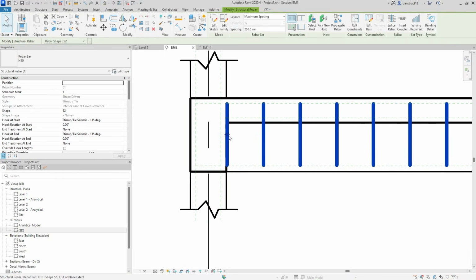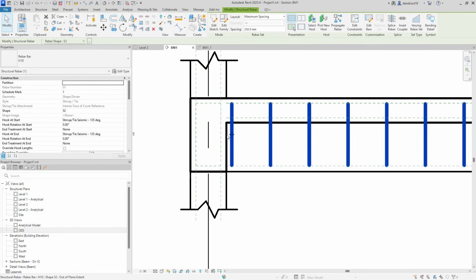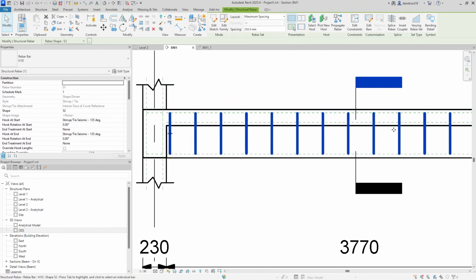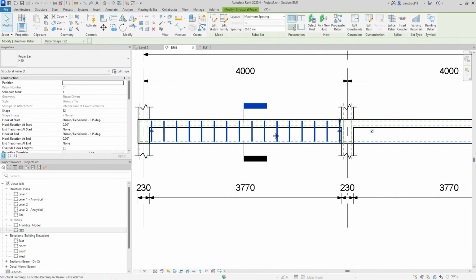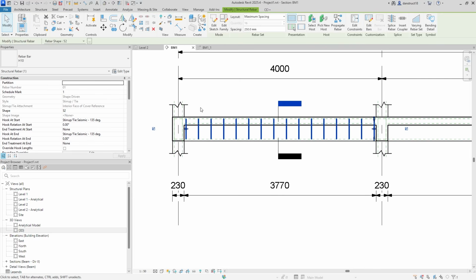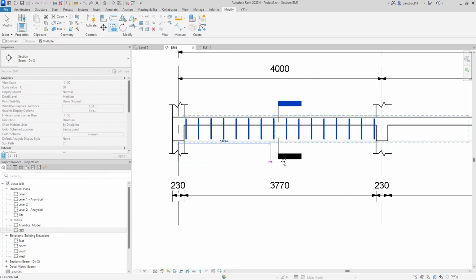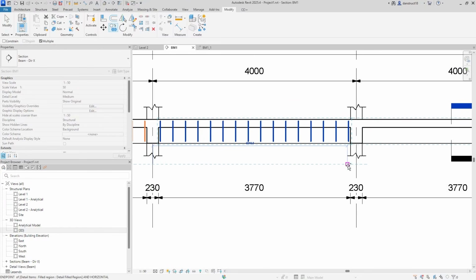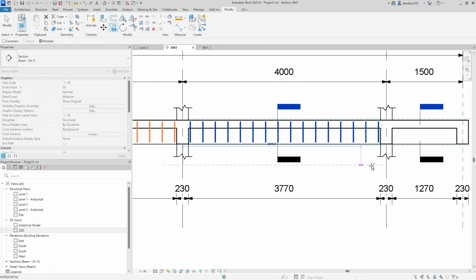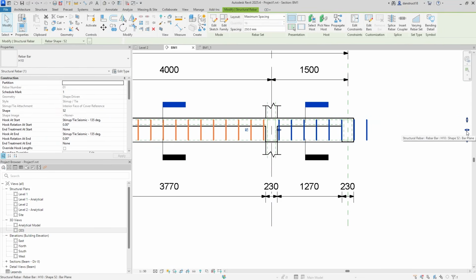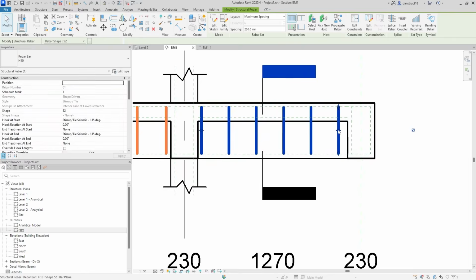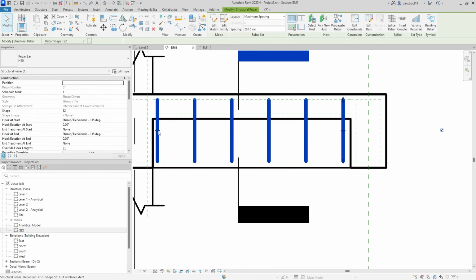Now I'm just going to go over here and adjust the position. I don't want to hit the face of this beam here. I could also use constraints, but for this tutorial that might be too lengthy. So let's just go ahead and place it like this. And once we've done that, we're just going to click on copy. I'll copy from this point here, place another one here, another one here, and one here. And I'll press escape. I'll click on this grid points shape handle here, and I'll drag it all the way to this point. There we go.